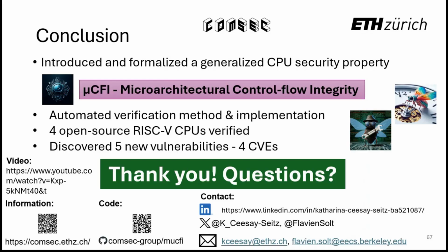I wrote my own assertions. And here we generated these conditions for reading, and we also automatically find this forwarding multiplexer and so on. So we don't use the interface. The existing interface captures the data too early for our property, in fact. And here it's mostly automated, and the property then is very simple. So it's really just checking, is there taint in the program counter?